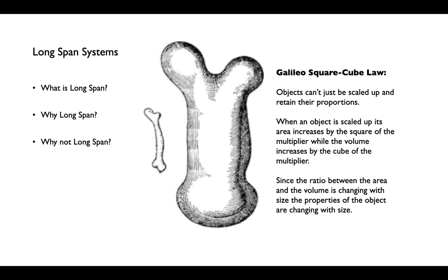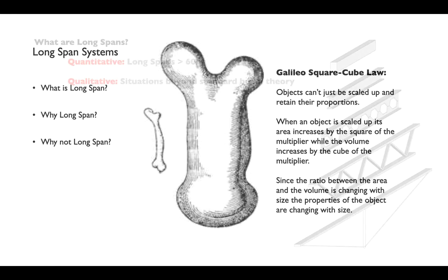So when we're designing a beam, for example, we're adding not just kind of depth to the beam, which is important, but we're adding volume to the beam, and therefore we're adding weight. And as you may remember, we get to spans where steel beams can't even carry themselves, right? They're carrying their own dead load, and as we increase the depth of the beam to carry that load, we're increasing the mass and the weight that the beam has to carry. At some point, we kind of start chasing our tail, right? We're adding more weight to that beam than we are adding efficiency or effectiveness.